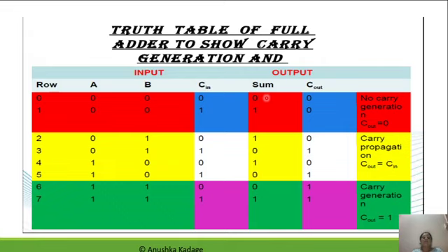So let's check the first row. Here the C out value is exactly similar to the C in. At the same time, in the second row also, the C out value is similar to the C in value. That means here, for generating the output carry, no separate logic will be needed. And we have the case that the output value for the carry is 0.